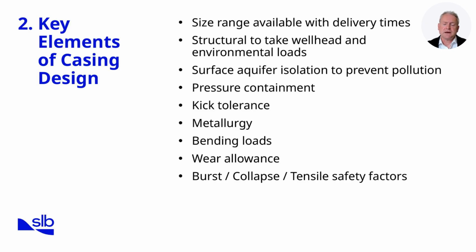We then evaluate mechanical loadings, including bending, wear, burst, collapse, and tensile stresses. Each load case must be analysed with safety factors to ensure casing integrity under both drilling and production conditions.